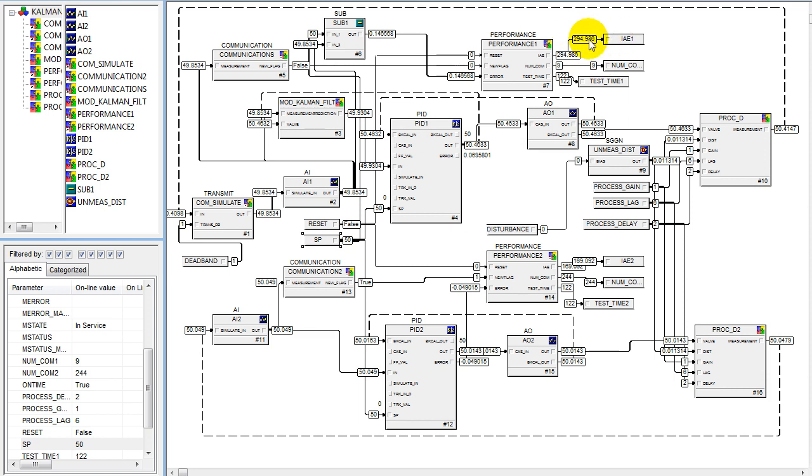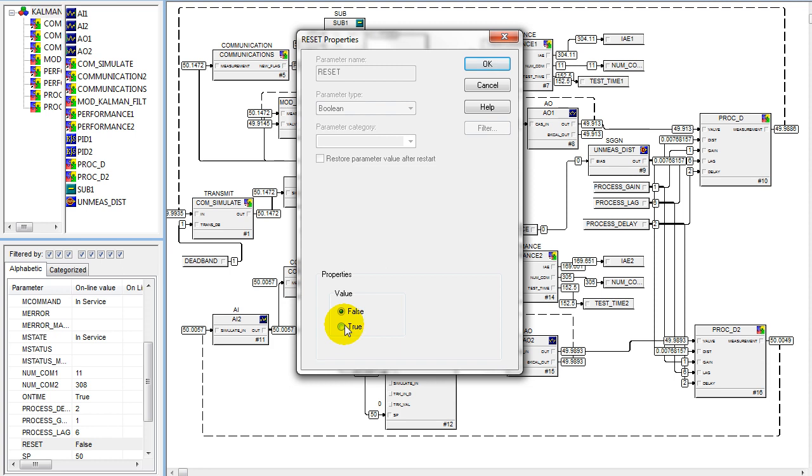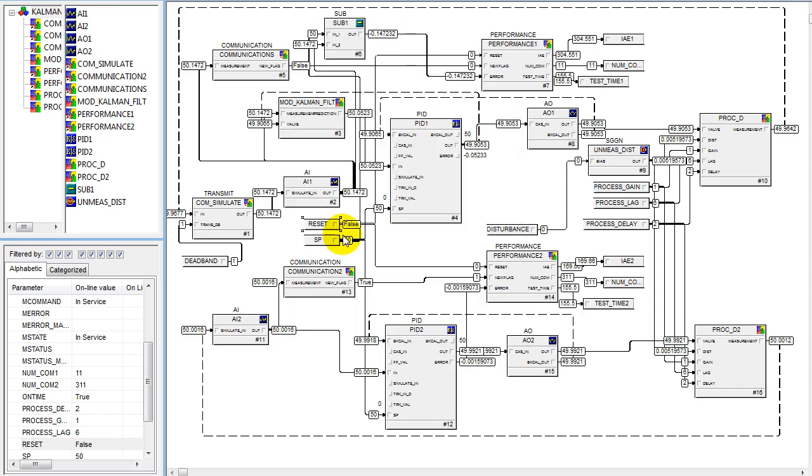If we compare the performance, we notice that the performance of the wireless control is a little bit worse than the wired control, which is what we'd expect. But for the number of communications used in wireless control, we only use 10 new measurements. And yet on the wired we used over 200 measurements in doing the control. So by combining the Kalman filter with the PID, we're able to handle wireless measurements using very few new communicated values.